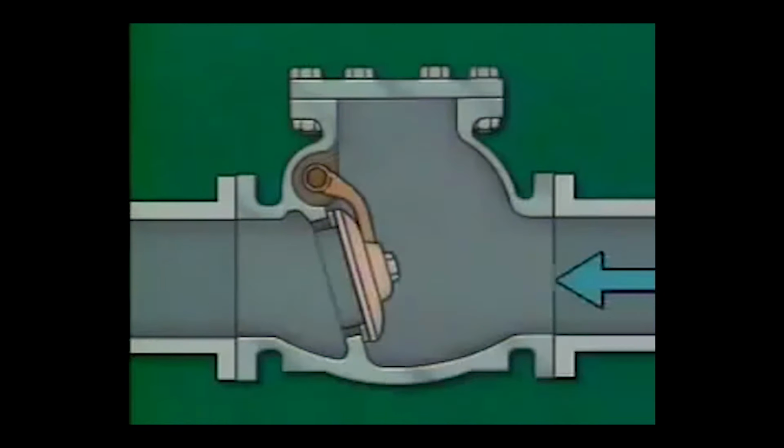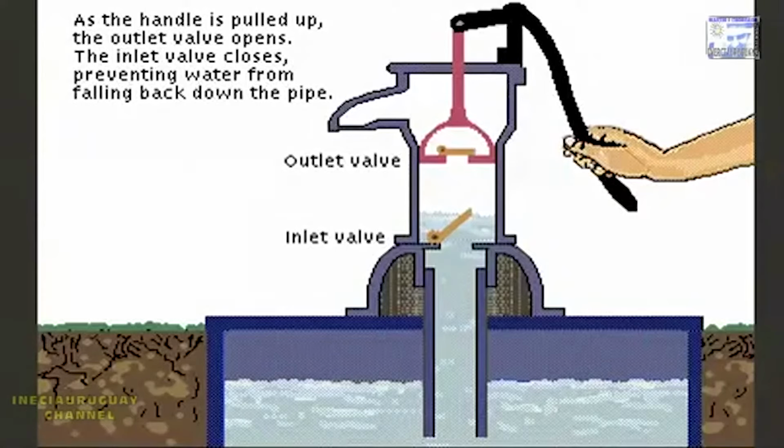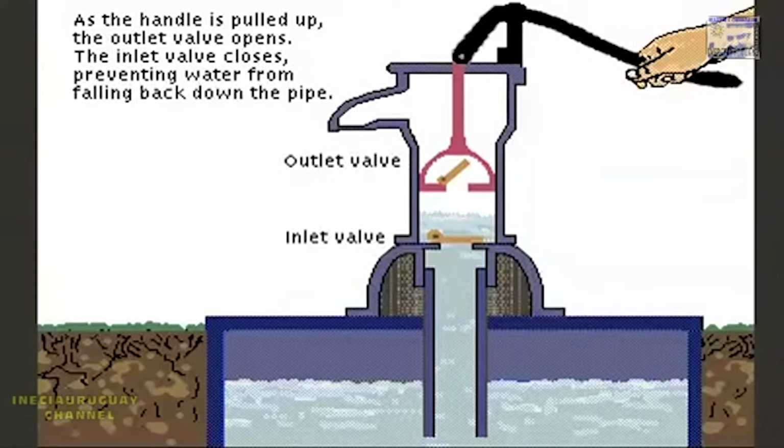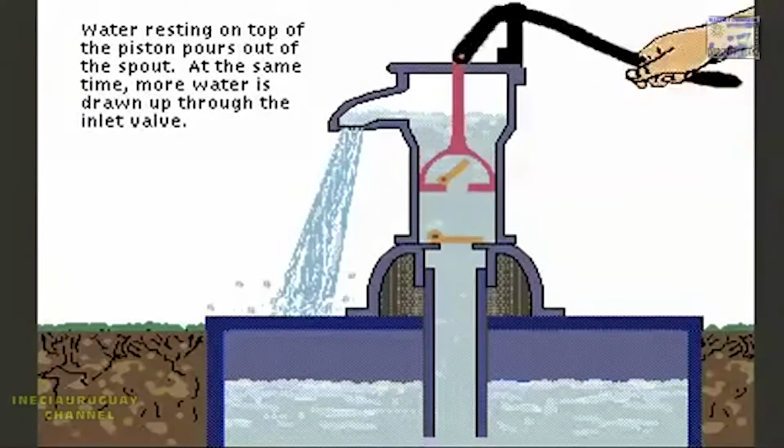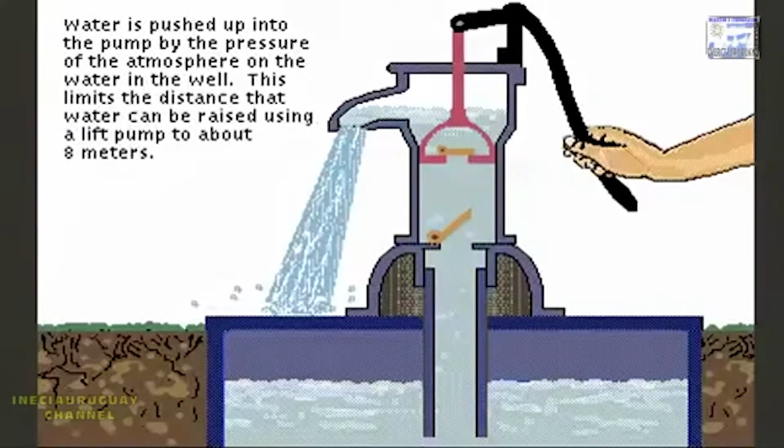But if pressure reverses and the liquid flows from the output to the input, then the lid will cover the passage, preventing backflow. The lid rotates on an axis, making it rotational. You need this in a pump to get the water into the upper chamber but prevent it from falling back down. With the second crank of the pump, the new water coming up will force the water trapped in the upper chamber out. Check valves are also really useful in chemical plants.